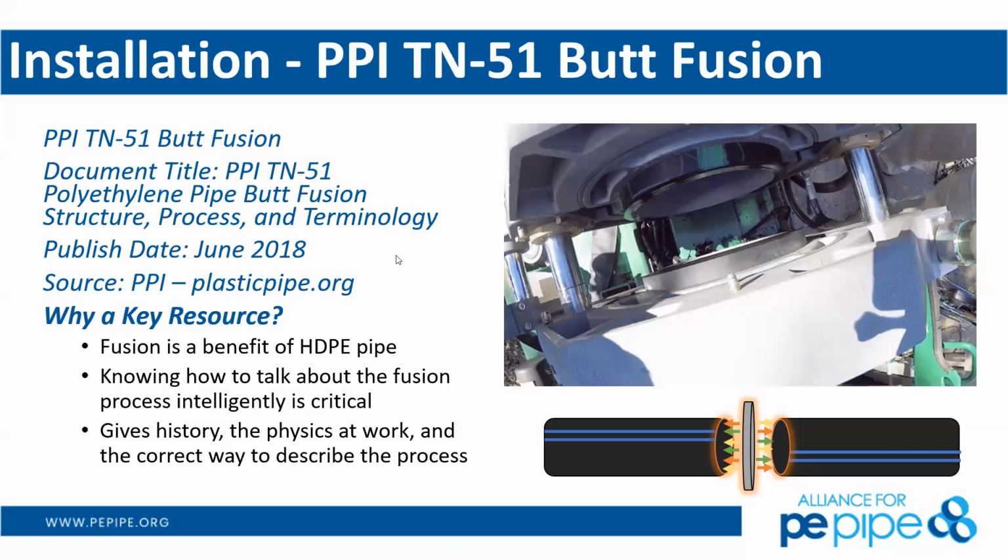So the butt fusion process itself is controlling the flow of molecules across the pipe interface in the field with appropriate heat and appropriate virgin resin. And by doing so, we get a joint that is as strong, if not stronger, than the pipe itself. Right, Rusty? Exactly.